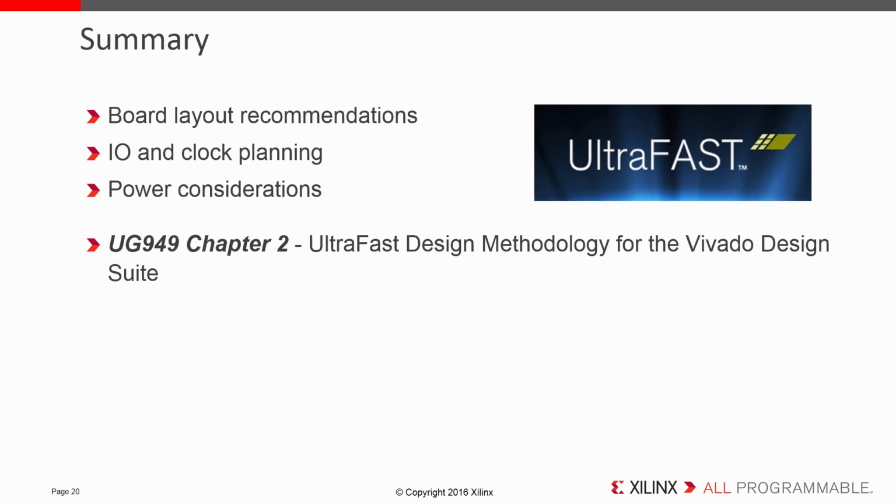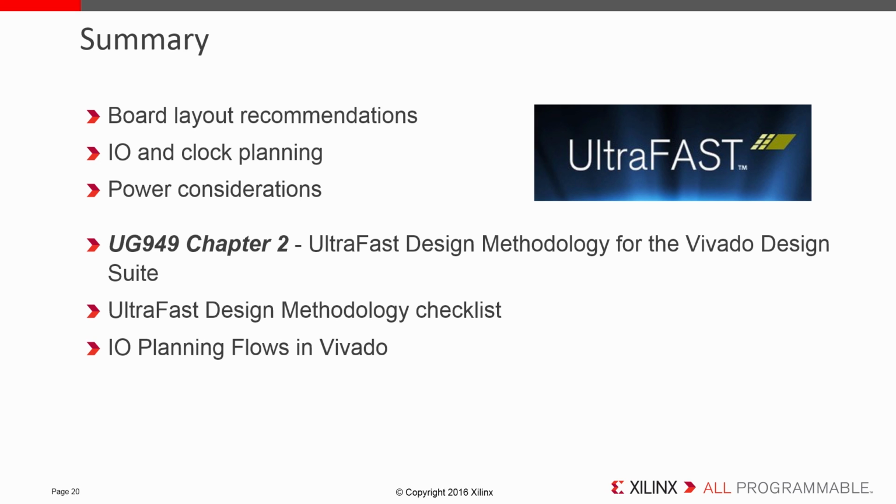Board and device planning is covered in Chapter 2 of UG949 and is supplemented by an UltraFast Design Methodology checklist in DocNav, and also keep in mind the extensive materials on I/O planning flows in Vivado.